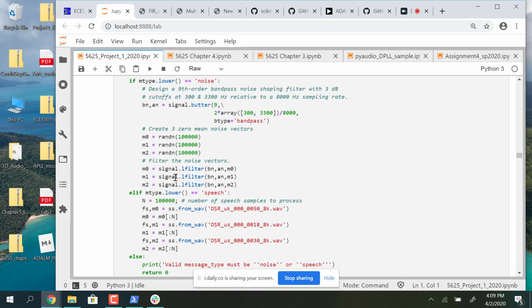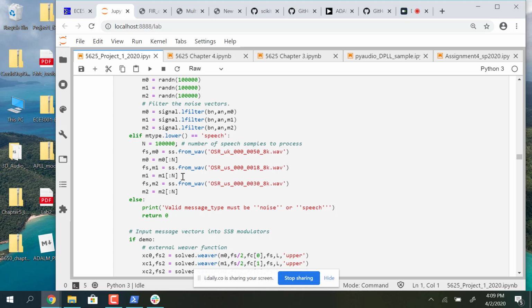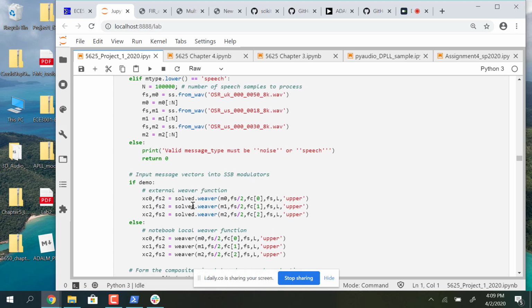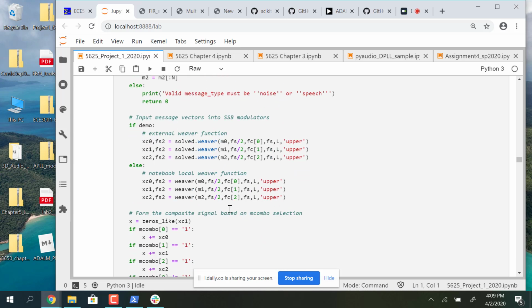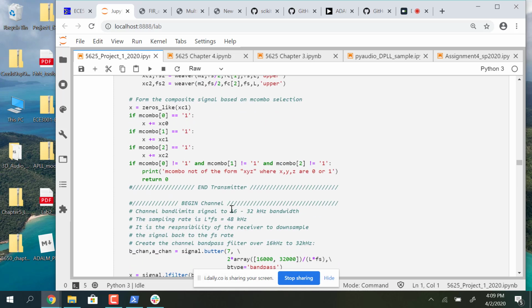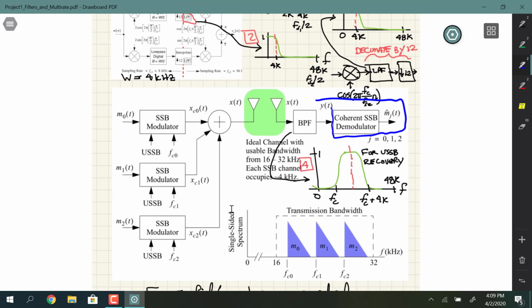So it's either this or this, and then that pushes into Weaver 3 times with the Weaver configured to set upper sideband, and then it drops in whatever carrier frequency you're calling for. It loads in your 8 kilosamples per second and just some other attributes that I have in here. Some of it's redundant the way I have it designed, but it is what it is. And then that gets transmitted. So that puts us back over to here. So we're sitting right here after we leave the transmitter.